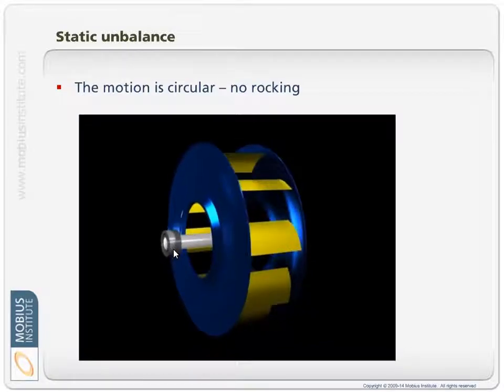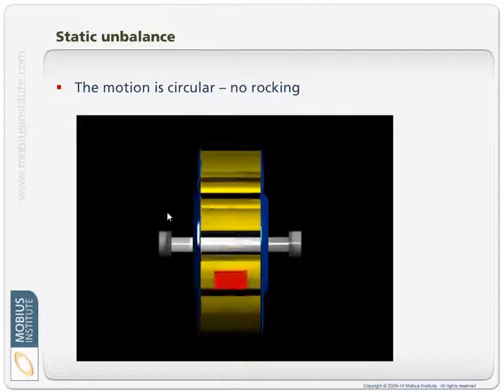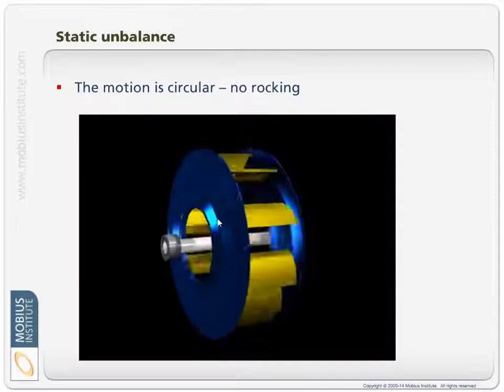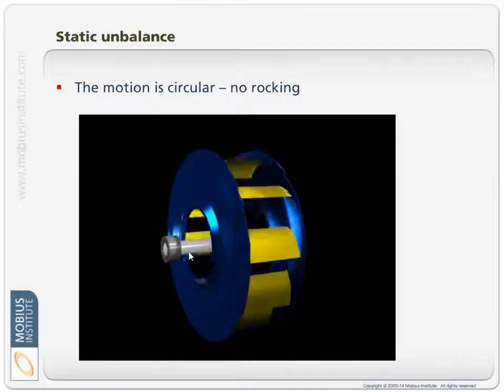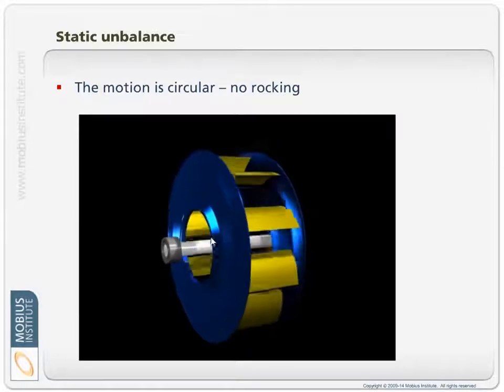So, that tells us a lot. From here, if we could take a phase reading, we measure vibration here, and we measure vibration here, and we see whether it's going up together, down together, up together, down together. If we compared the vibration vertically here to horizontal, we would see that they're both going up and down, but there's a quarter of a rotation delay between the two. So if you look at it, it comes out to the side, then up to the top, then out the other side, then down the bottom, then this side, up the top, and so on. There's a phase timing relation.